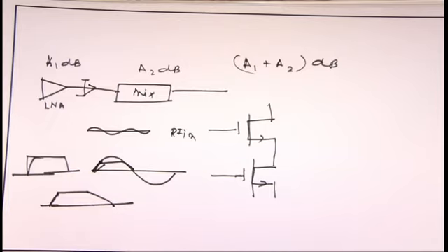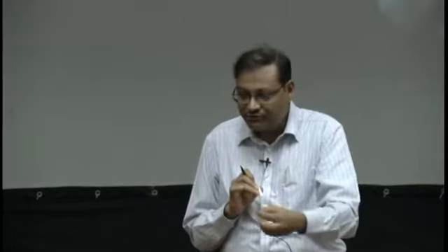So there is always a little bit of confusion whether you go for a rectangular kind of local oscillator or a pure sinusoidal one, because your VCO, what is the problem? VCO will give you sinusoidal signals. So the question is whether you require a wave shaper to make it square or rectangular before it is fed to the mixer, or whether it is just fed directly.